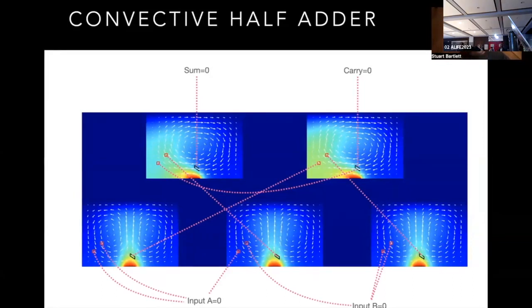So what does that mean, 0.05? Well, basically, 0 would mean complete thermal resistance, i.e. no heat transfer across the line whatsoever. And 1 would imply perfect heat conductance, so no resistance whatsoever. The heat would flow directly across that thermal wire. We found that 0.05 was a good compromise to avoid noise and transients and spurious information transfer.